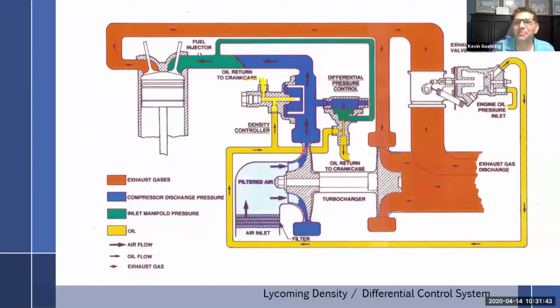I read 2 books. Okay, so oil comes around, goes through, it flows through here, drain to crankcase. Okay, that's an important point right there. As long as this drain is open, no oil gets to build up in here. It just comes through here and goes to drain. It just takes a long way through drain, and it goes through a bunch of controllers.